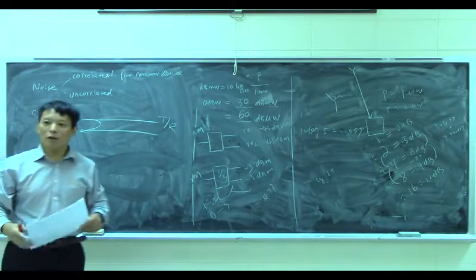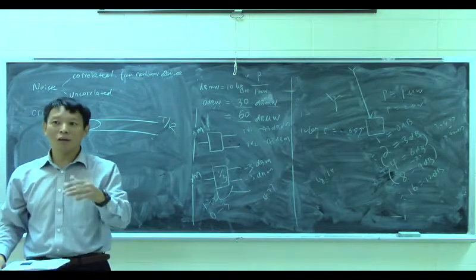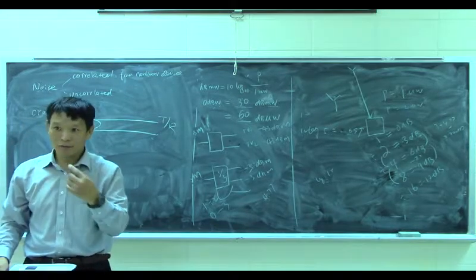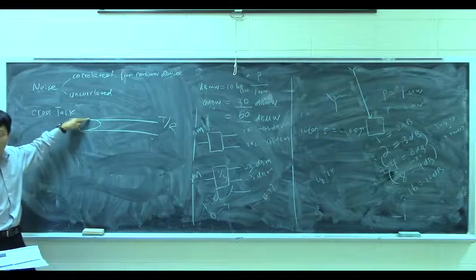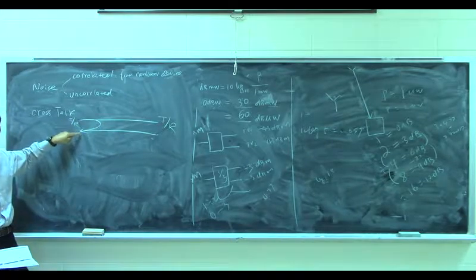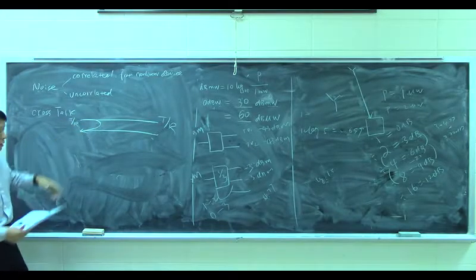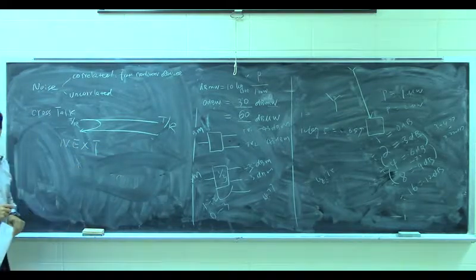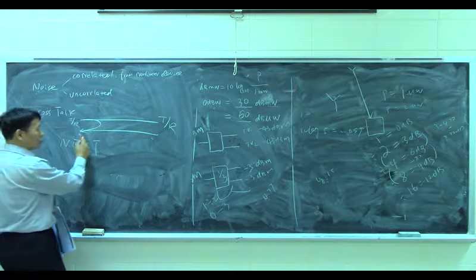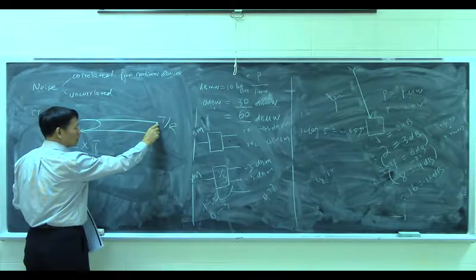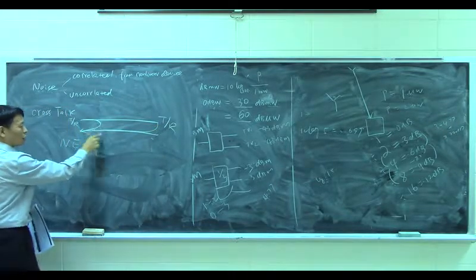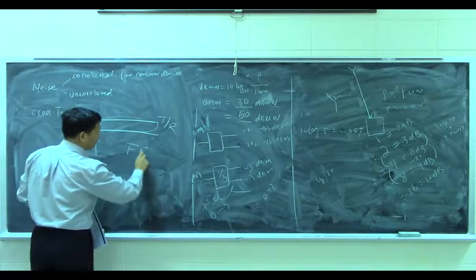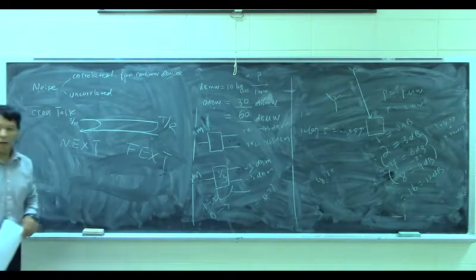for example, if you make a call with your computer, sometimes you hear the echo. The echo is from yourself. That is this. You make the transmission, but you hear your voice. Right? That is called near end crosstalk. If this noise is from here, linked to this part, and comes here, this is called far end crosstalk.